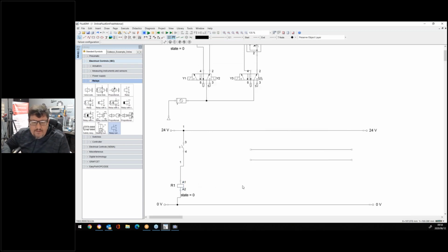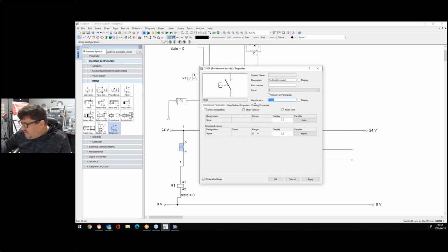Right, there it is. Right, now my push button, and you can label also the push button. You can double click onto the component. It will open the properties of this component. I'm going to click it down there, put the PS. Not PSP, PSB, push button number 1, for example, right? And I'm going to say okay, so you guys can see it when I click apply.